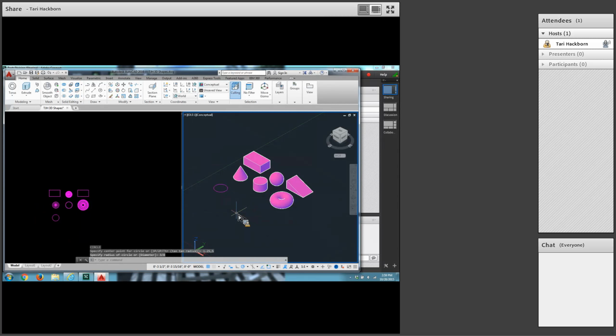Okay. On the next page, they want you to do something with this circle. They want you to use the extrude command on it. Select extrude, select the circle, and enter. Type T and enter, or come down here and select taper, either one, taper angle. And then type 15 for your taper angle. And make sure you're dragging upward when you type 1/2 inch. Enter. Okay, there we go. I think I hit the shift key instead of enter.